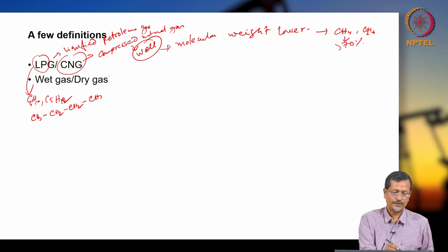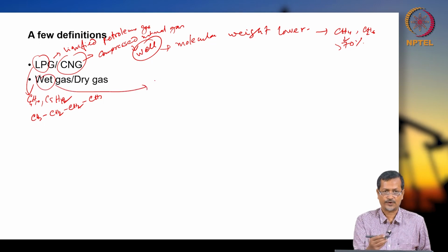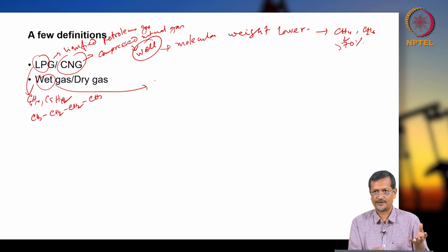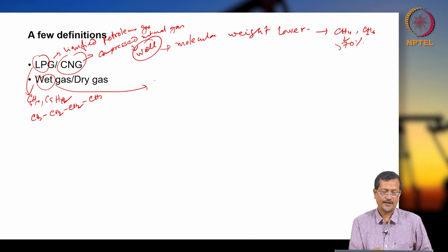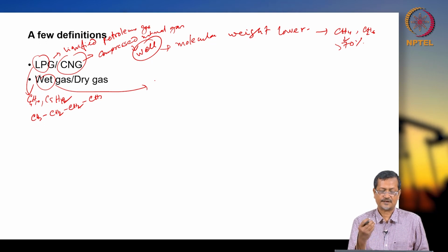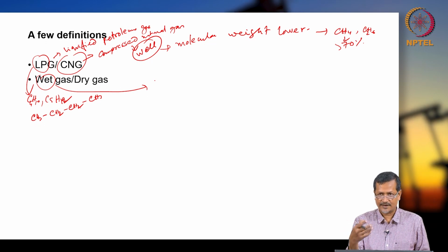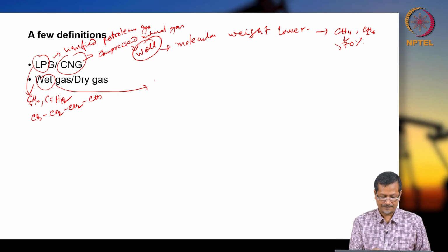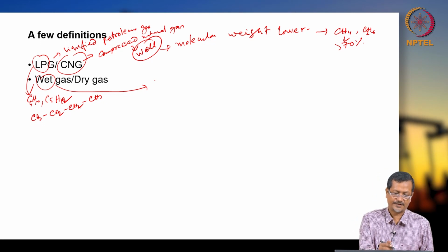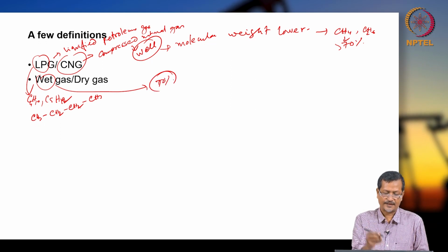And what is wet gas and dry gas? This wet term is not related to water. In general, common people understand wet as water soaking something. But in the oil and gas industry, wet means we assume that some liquid particles are also there in the gas, or a liquid is soaking something, which can be water or oil. Dry natural gas contains more than 70% methane and some ethane.